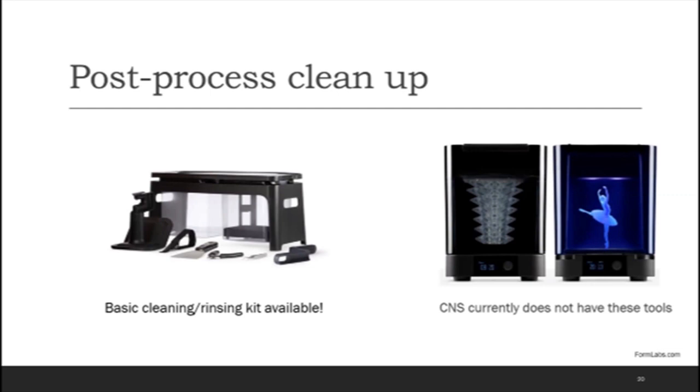However, I do want to mention, because maybe people already know that these 2 tools exist, the Form Wash and the Form Cure are something that FormLabs has available out there. Unfortunately, we don't have this at the CNS, but it looks like it's really easy to just put the platform in there. It sonicates your print with IPA, and then you can immediately cure it.